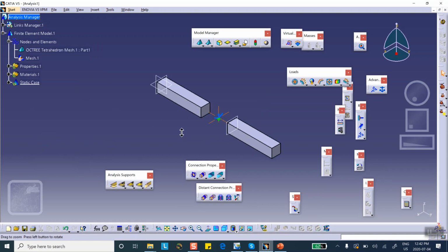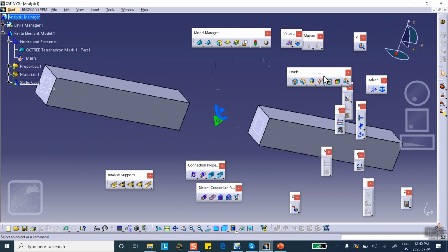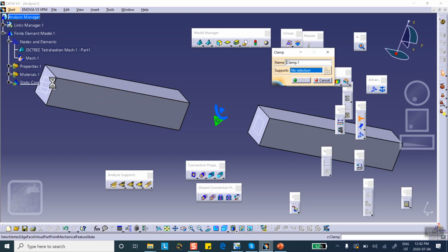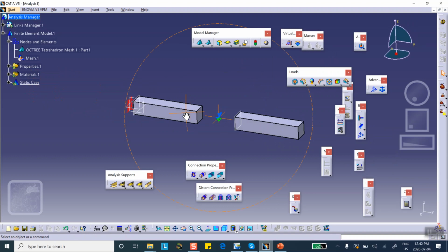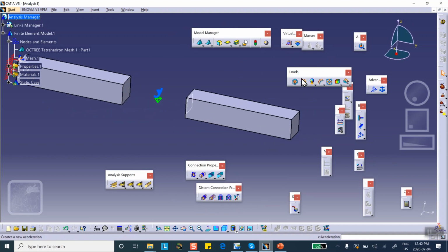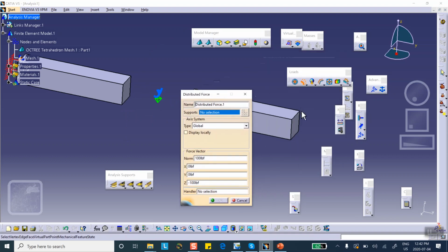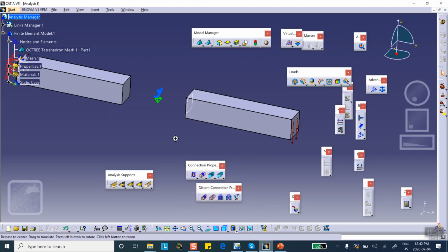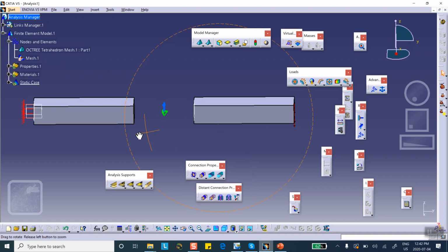Okay, so first of all, I want to clamp the side, clamp this face, and apply 100 pounds on the face on this right side. This face, downward. Okay, and then we want to create a connection between this face and the one on the left.